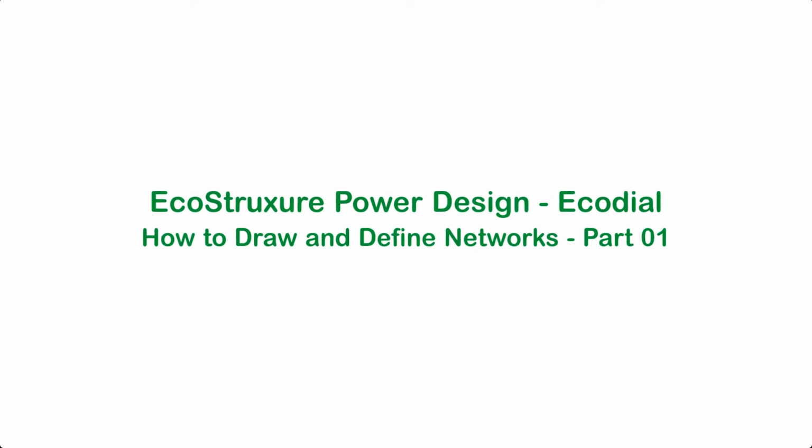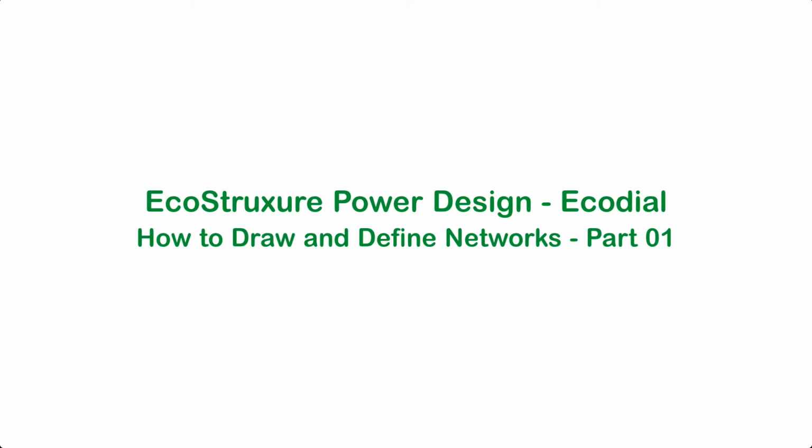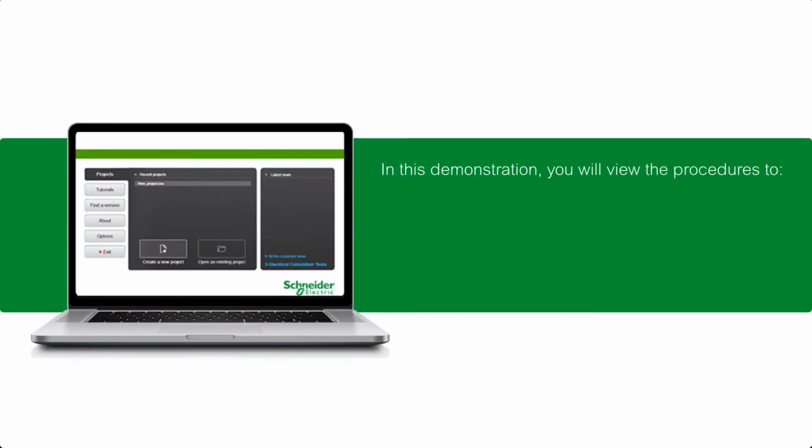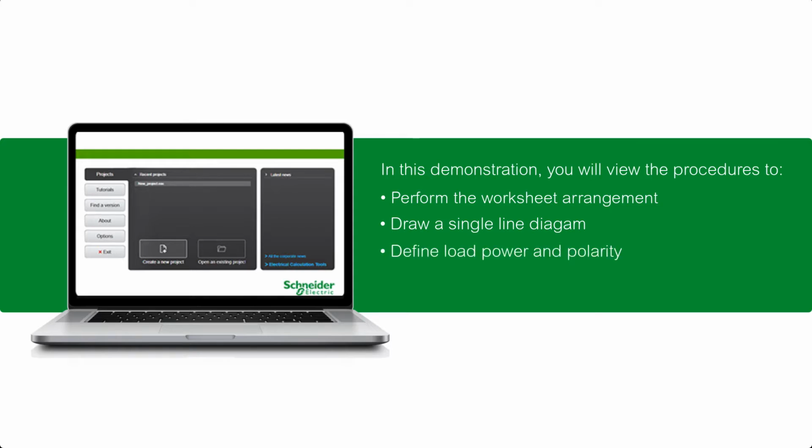Welcome to the first part of the video tutorial on how to draw and define networks in EcoStruxure Power Design Ecodial. In this demonstration, you will view the procedures to perform the worksheet arrangement, draw a single line diagram, define load power and polarity, and define system earthing arrangement.